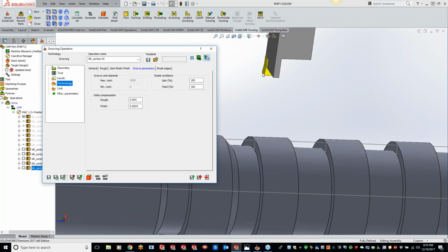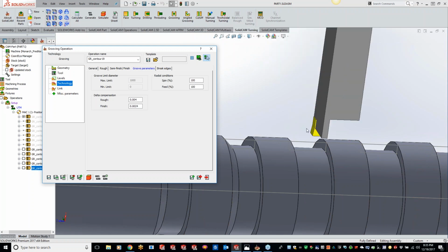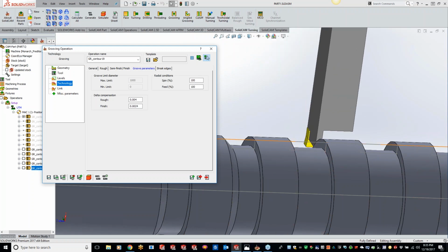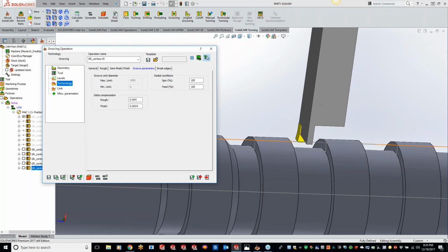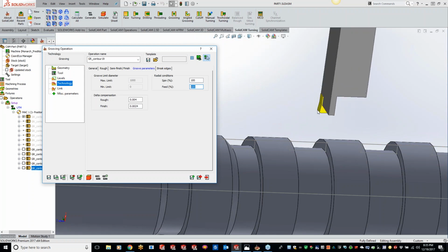These grooving inserts are more meant for going straight down, not so much for going sideways. We can't put a lot of pressure on the side. So we can turn down our spindle and our feed rate, whatever you want, for the side cutting, but at least we're utilizing the full amount coming straight down into it because we're putting direct pressure down in there. So this is just for the side cutting only right here.